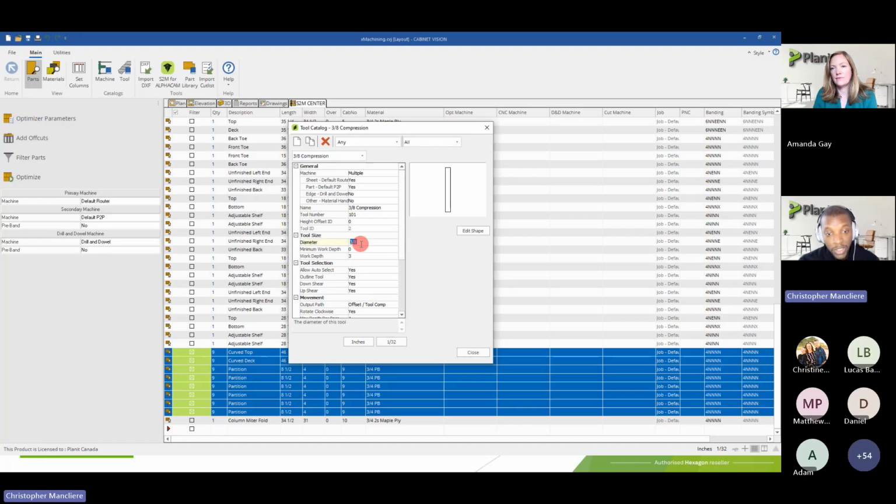And that's why it's important, on the CNC machine, rule of thumb, and that's really important, the tool will be equal to the one in CAD if, when we measure it, it's exactly the same, or smaller if we sharpen it and it becomes a little bit smaller. The smaller, I would say, there's a limit. It shouldn't be smaller by, for example, an eighth of an inch. It should be some very small value.